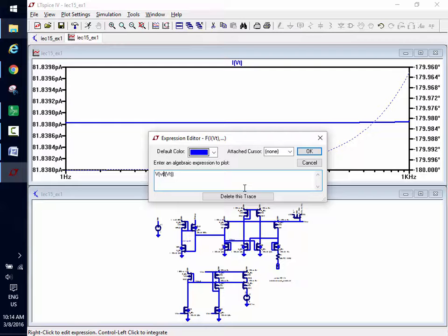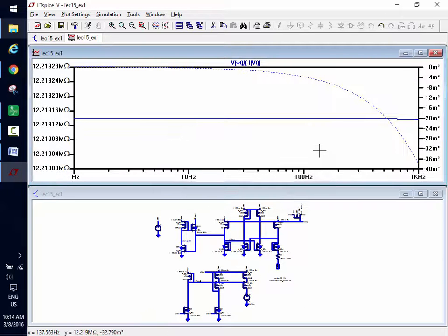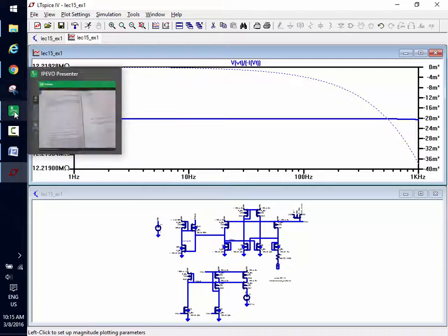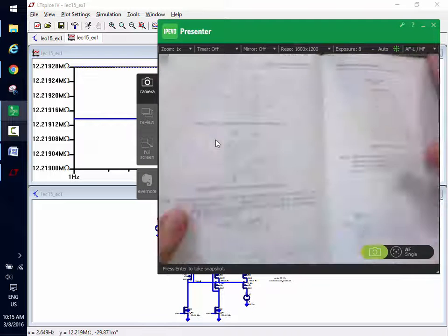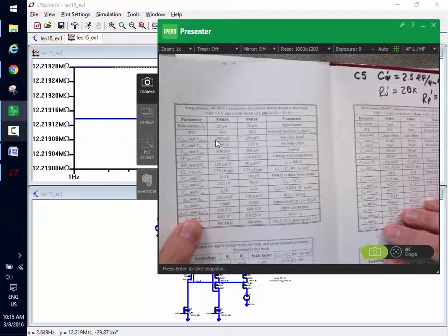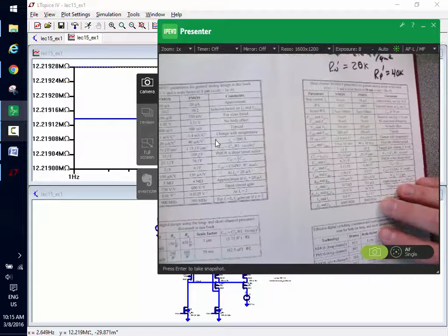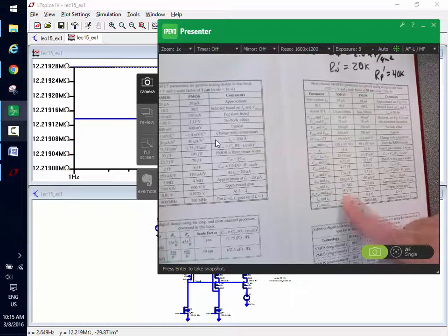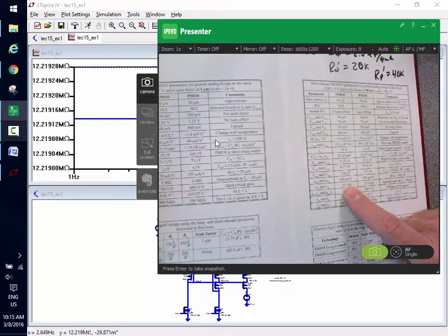There's so many examples of plotting output resistance. And you mean you give me examples, you want me to look at them? Yeah, so it says 12 meg. I'll hit save on there, and then I'll go back to the book. And let's just compare what I just did there to table 9.2. And GMR out is 25, and R out is 167.